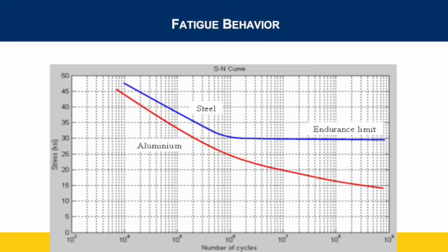So this is what we typically see, and there are some interesting differences. One is aluminum. Say we have this aluminum that's been strengthened. When we put it in the Instron machine at close to 0 cycles, we get a yield strength, which we'll call sigma ys for yield strength, of about 52 for the aluminum. The steel was around 60, so it's a pretty strong aluminum. It's been alloyed so that it's almost as strong as steel.